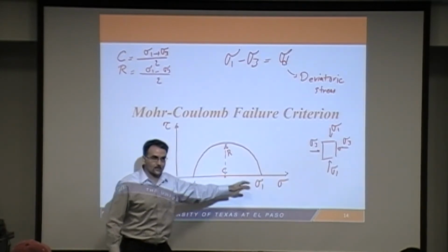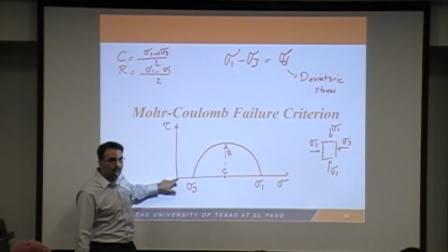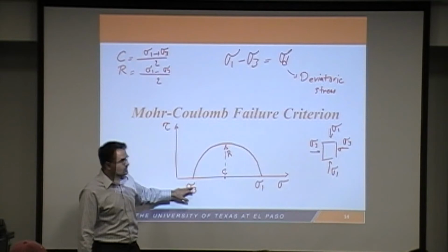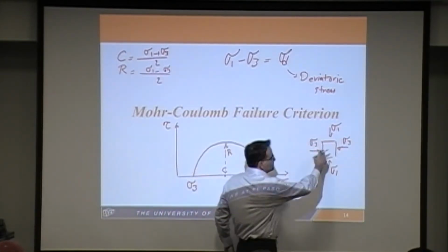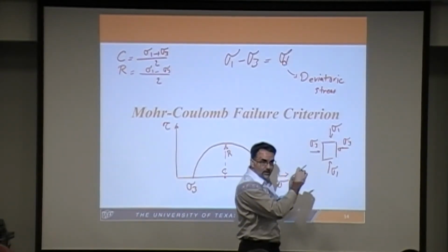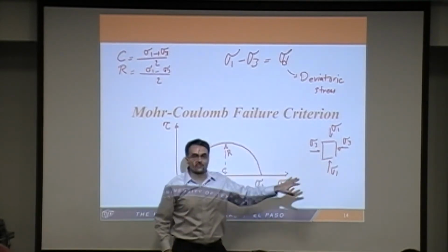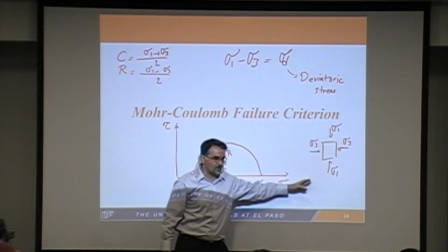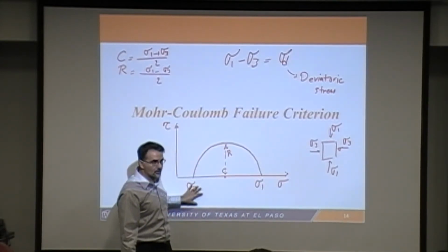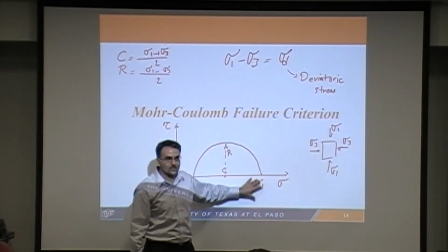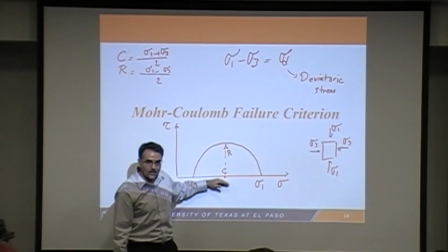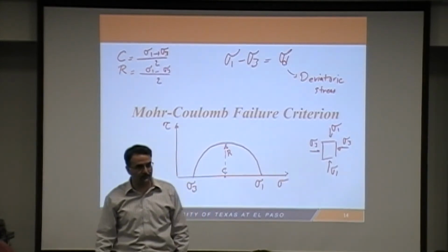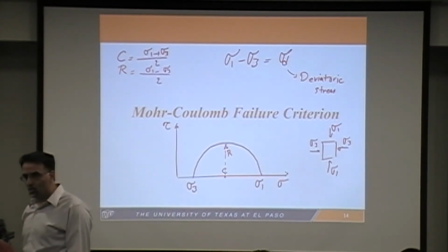The x-axis, right? The shear stress is 0 right here. Therefore, your sigma 1 and sigma 3 are principal stresses. Notice that I didn't put any shear stresses all around this element, so it is free of shear. The stresses are principal stresses. So principal stresses are the stresses happening on the principal plane, and the principal plane is the plane on which the shear stresses are 0. Right? So that's coming from your Mohr circle.